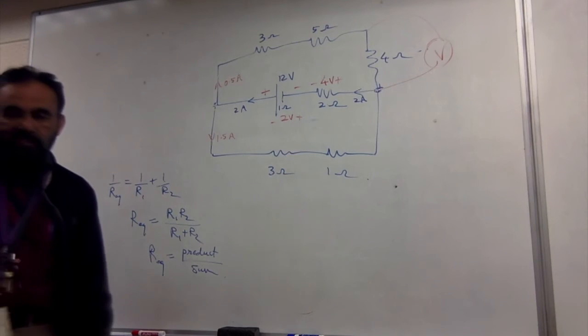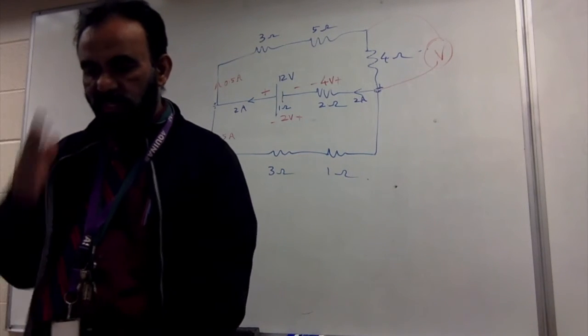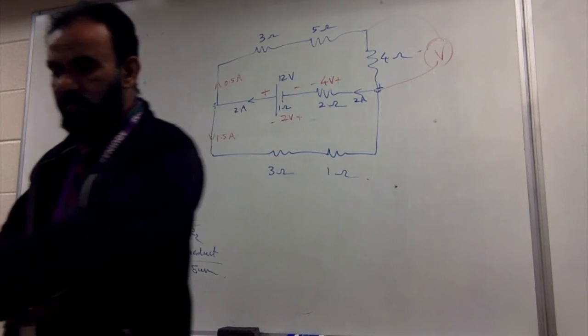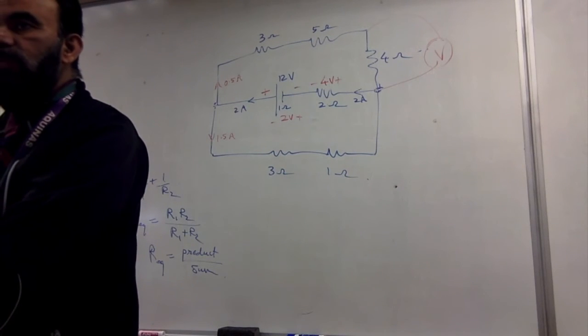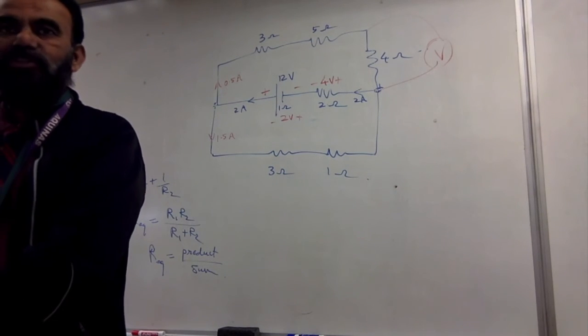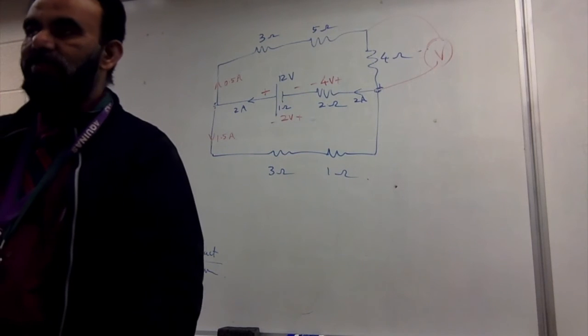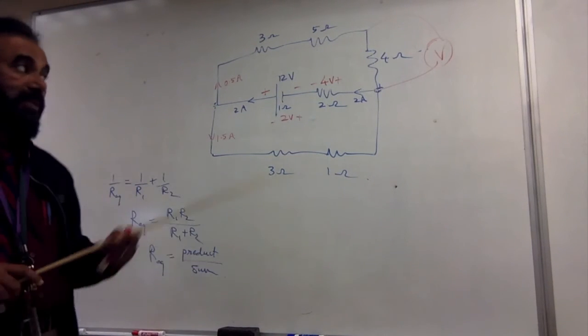So in a circuit, you know the numbers, and so you can anticipate, okay, according to these numbers, I'm supposed to get 2 volts here. And then you check with the multimeter and it does not show 2 volts. That means there is some defect in the circuit. It could be from anywhere.